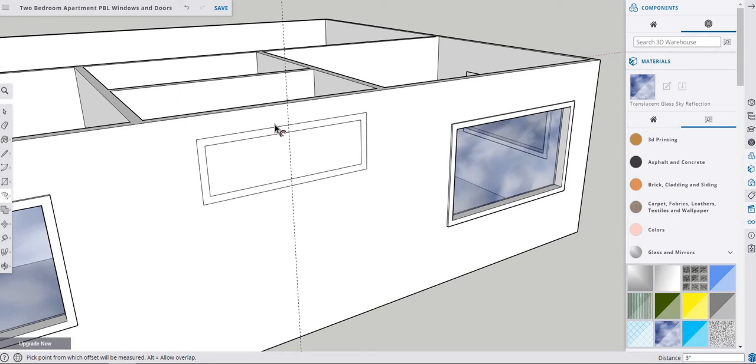The next one we're going to do is go back to that measurement tool. Not tool, sorry, this tape measure tool. We're going to go from here, and then go out like this, 1.5 inches, and hit enter. So I can drag from here.